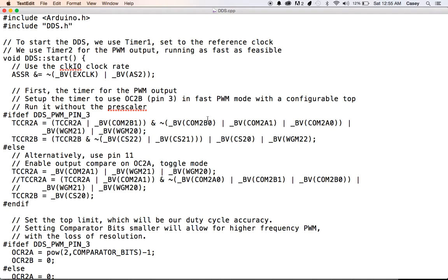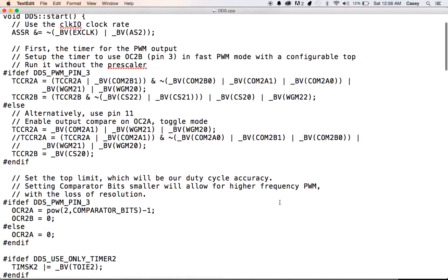And this kind of takes it a step further to get all the timing right, to make sure that we actually produce quality waveforms. Because I'll tell you that if you have a very bad waveform, or you were just playing tones like I was trying to, it's very dirty, and the decoder on the other end won't know what the heck you're doing. So it's very important to use accurate tone generation.